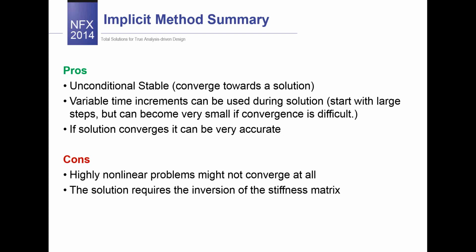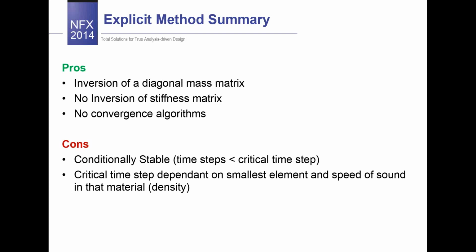The achieved solution is very accurate via the implicit method, but as we discussed previously, we have to pay for that because the solution requires matrix inversion, which is a computationally costly process. And this method is valid for long-duration dynamics, let's say, where the event time is relatively long and nonlinearity is on the middle level.